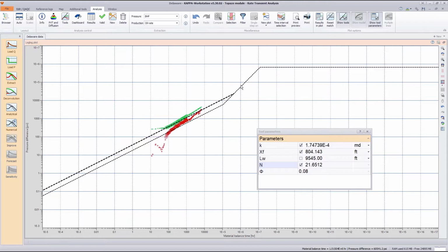Then we know that this well was completed with plug and perf completion technique. It had 42 stages with 15 fractures each, so that it will give us about 330 fractures in total with probably a short fracture half length.